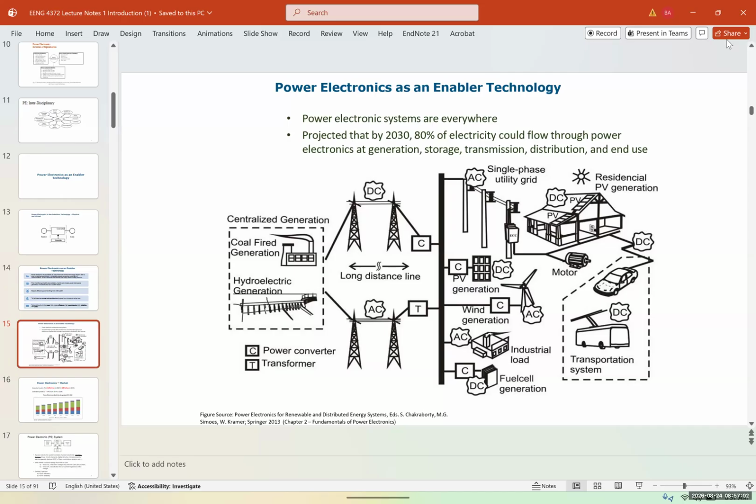The problem is that we have solar in the middle of the day when we don't need it that much, but a coal power plant could run 24/7. Solar, you obviously can't use at night. So how can you solve that problem? With storage. Now, storage could be done in different ways. They can use chemical storage like batteries. They can use hydro dams that pump water to a higher elevation and then release the water at night and generate power. That's like 60-70% of stored energy in the US right now.